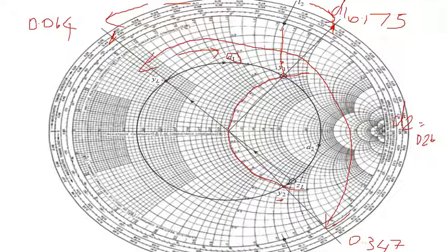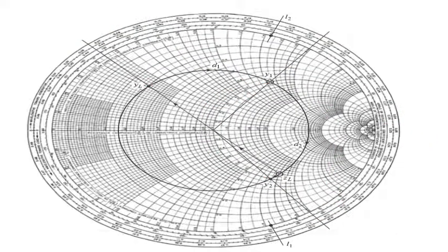To make the imaginary value equal to 0, in this case, you can also check that for this Y1, when you are marking, you have got plus j1.43. So the real value of this over here, you have all seen it is 1. And this, you have to cancel it out. So what do I do? Take a complex conjugate of it. So this plus j1.43 has to be marked down as minus j1.43. That will come approximately here.